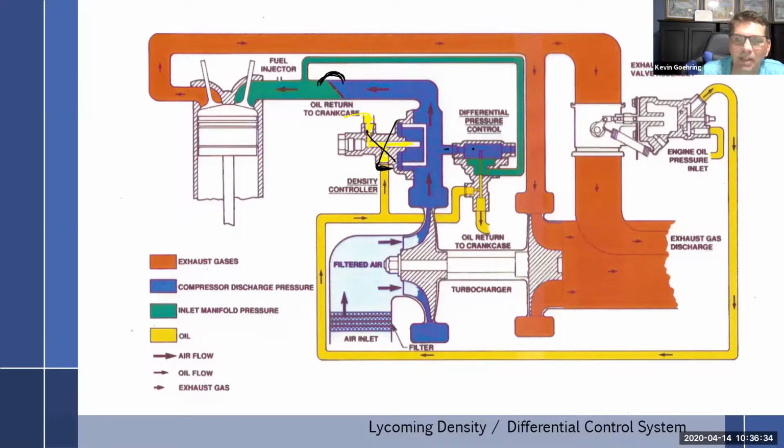And it says, wait a minute, let's think this through here. We shouldn't have really more of a spread than a couple of PSI across here. Otherwise the turbo is just working too hard to build up all this density we didn't need anyway. So let's just measure across here and give it a couple of PSI. I'm just going to say 2 for right now because I remember what it was off the top of my head, but I think it's about 2 to 4. So we're just going to hold this here at about 2 to 4 PSI. Anything more than that's ridiculous. We don't need it, and it causes turbo sensitivity.